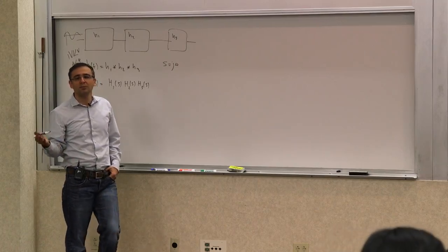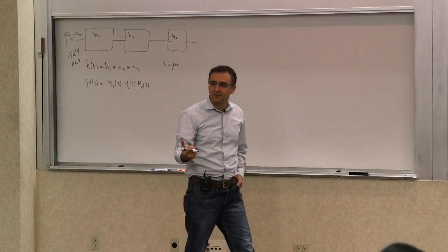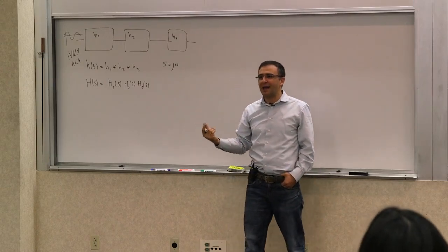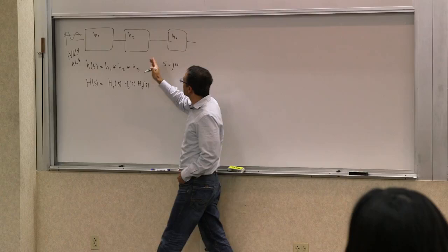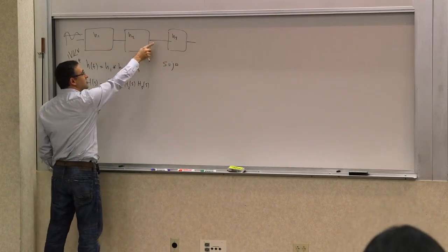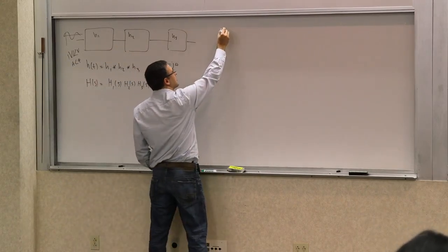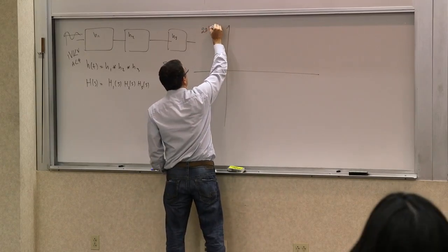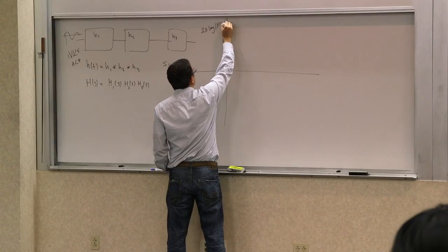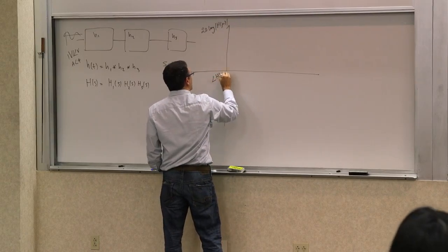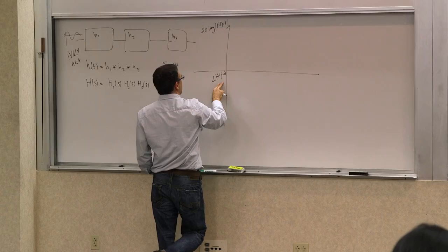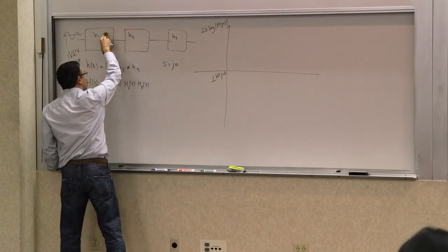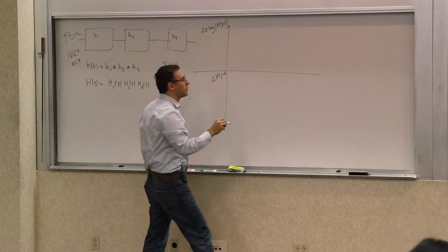So we said that Bode plots was a way of plotting these things. And it was useful because being a logarithmic representation of the magnitude, it allowed us to convert this multiplication to a summation. And the Bode plots that we created looked kind of like this. So for example, you had 20 log of the magnitude of H of j omega and the angle of H of j omega. This being logarithmic and this being linear results in being able to add the Bode plots associated with the system in cascade to produce the overall response of the system.